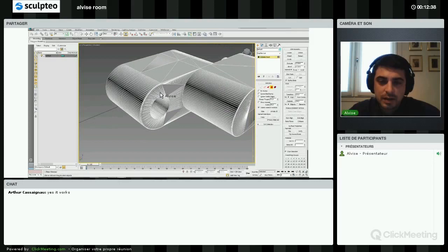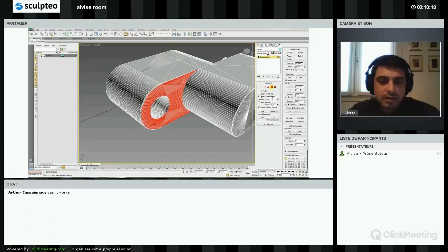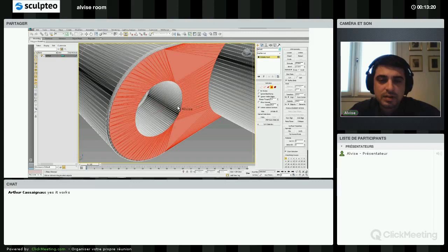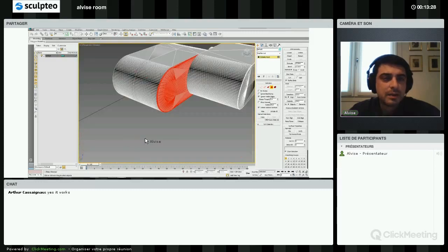I'm now just selecting polygons, so I want to select all these planar faces together. So I'm using this option, ignore vertical edges, and then I want to play with the threshold. So this is too high. I will bring it down to around 10, and okay. I select everything I want. So all I have to do now is select and move, to move the space, and to move it precisely the dimension we want.